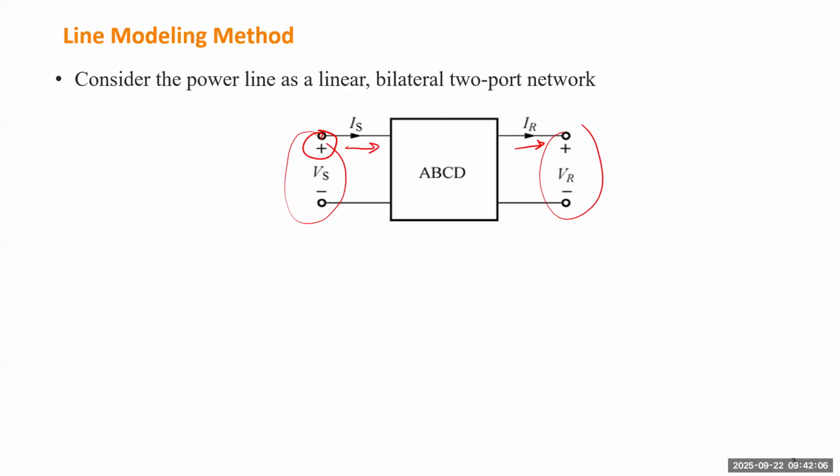depends on calculation. If you remember how we use the phasor diagram to determine the angle difference between the voltage and current phasor, then we can decide the signs for P and Q, right? So we have to draw P and Q in the complex plane to know this equipment is really an active source or reactive load, or active load or reactive source, right?